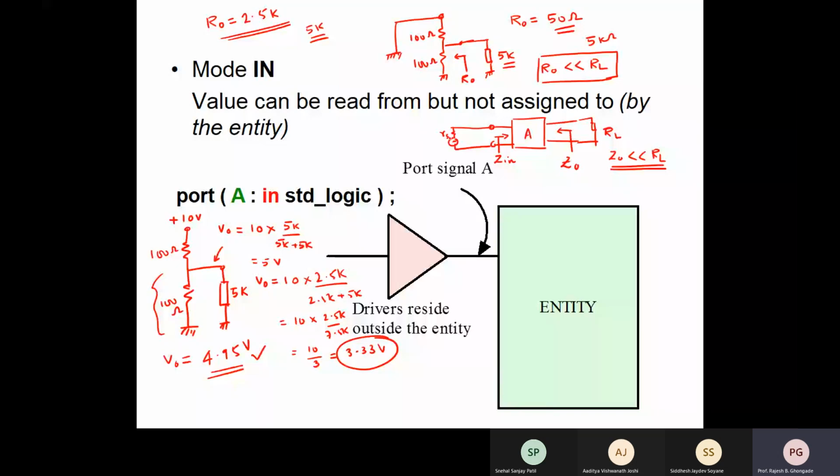What about the input side? Again, there will be loading at the input side because of the input impedance of the amplifier, no? Yes, similar line, I should say RS should be very much small as compared to Zin, or Zin should be very high as compared to RS. Clear? Yes, sir.